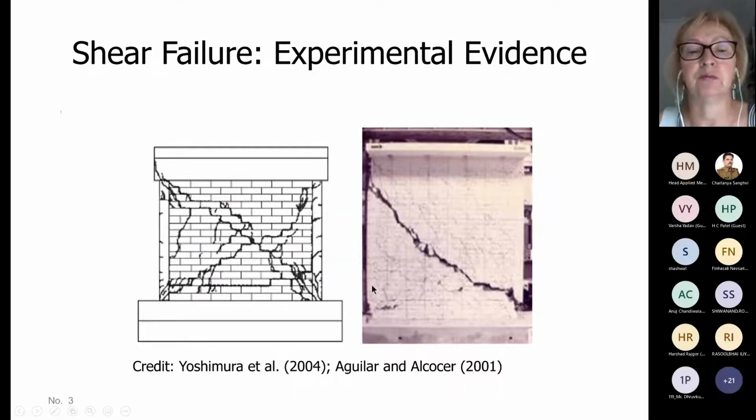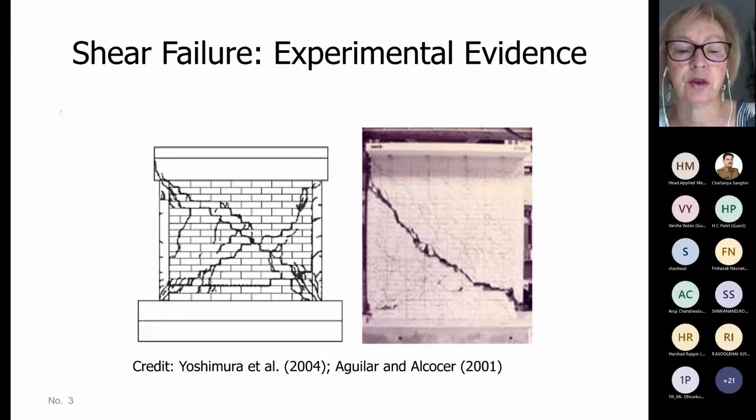Professor Dr. Juan Jose Perez Gavilano, in his lecture, also showed some photographs of the testing. There were numerous tests of confined masonry walls, full-size walls, in different countries. There were some tests in Japan, for example. The diagram on the left and the diagram on the right are tests from Mexico. You can see that the right-hand side is the stage of failure, that is point 3. The left-hand side is more like stage 2, where there is cracking in the tie columns as well.